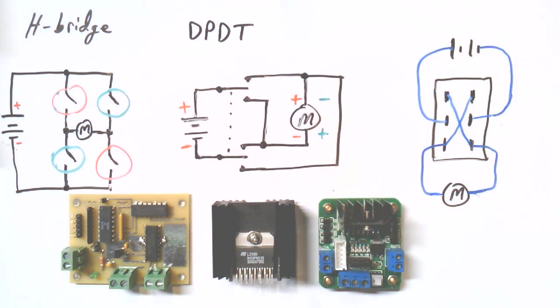So you can see down the road we'll be getting into maybe some of those things. I mean, I'm a little ahead of the game here mentioning it, but they're very versatile. The H-bridge, you know, speed and direction for several different types of motors all comes into play. And some of the extra chips, I'm guessing in this example, would be your dual H-bridge, just because it's got some heavy duty current capability.